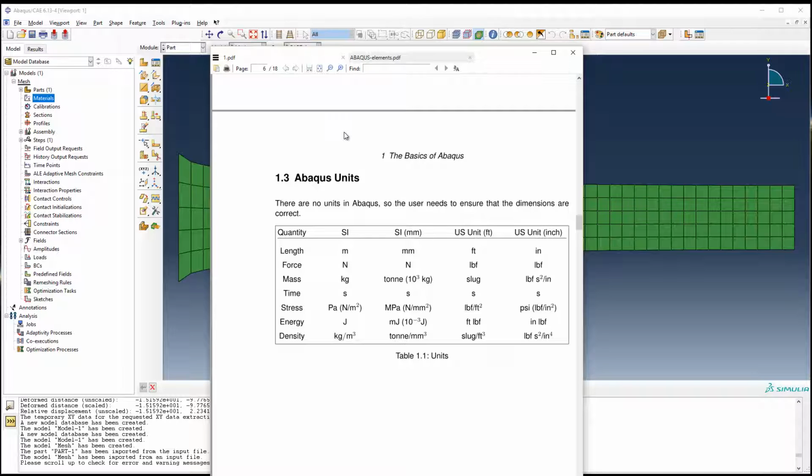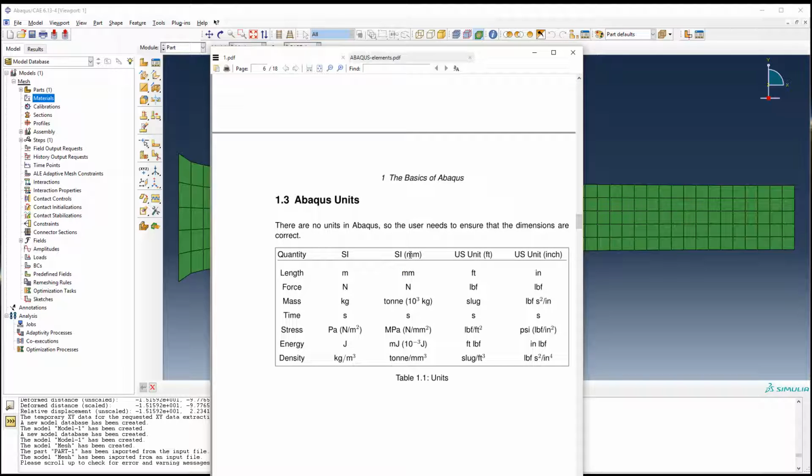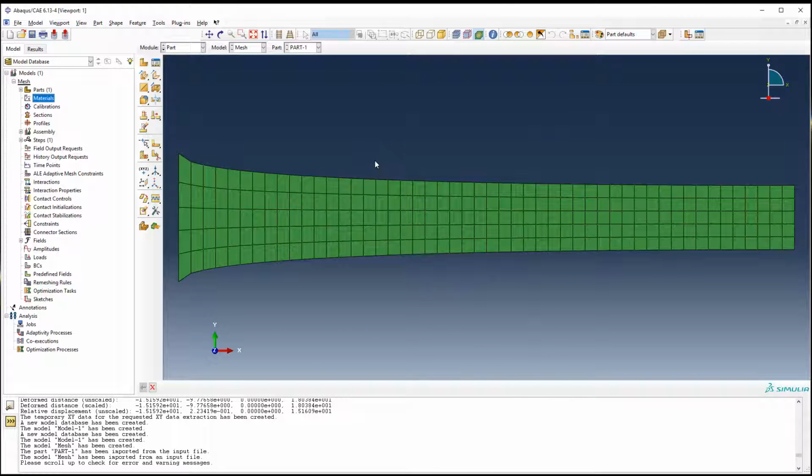If you're using engineering units, you might use millimeters. In the visualization videos, I didn't use millimeters. I used meters, and that's the reason why everything was a little bit weird in the results. So let's do meters now and see where that takes us.